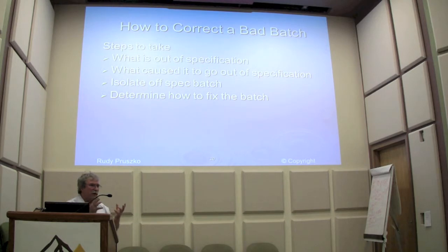So that's what too much water at high temperatures will do. But what if it's already mixed with the methanol and the catalyst? Would it not just make soap, or will it actually make an FFA and then make soap? Yeah, FFA then soap.